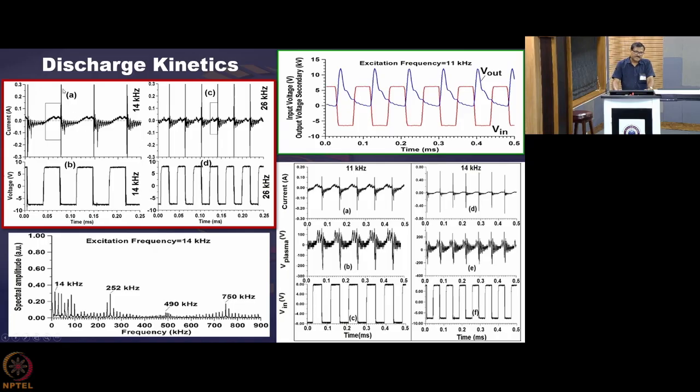So the important part is that the plasma is created very momentarily, and it is not a continuous plasma. So here you are getting the pulse, the plasma is formed, then again there is another pulse which is causing the plasma. Because it is created intermittently, the temperature of the plasma cannot go very high.